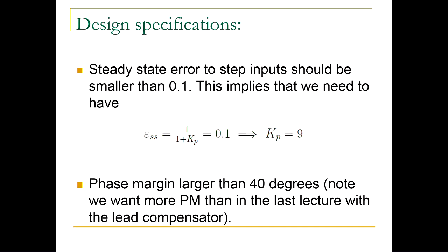But, you know, by doing it with lag, you can then choose the gain of the compensator and corner frequencies in the low frequency range, so that the compensator would have some lag, but it will have it here. But it will have moved the crossover here where the plant had more phase margin itself. So that's the philosophy behind the steps.